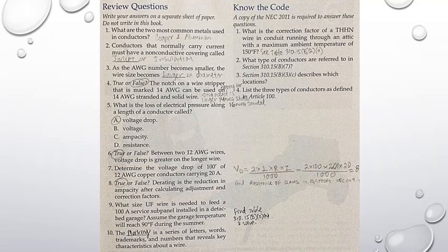Voltage drop equals 2 times length times resistance times current, all divided by 1,000. In this case we have 2 times the 100 foot of length times the resistance of 12 AWG copper, which is 2.01,